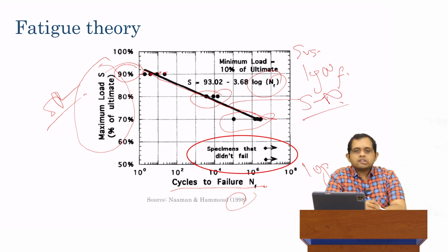Using this curve, if you have such and such stress ratio based on your loading, that could be external loading, that is vehicular loading, it could be climate-based loading, but based on whatever loading you have, if you can calculate using whatever theory the stress ratio in your JPCP, then for that stress ratio, you can calculate NF, which is the number of cycles to failure for that stress ratio.